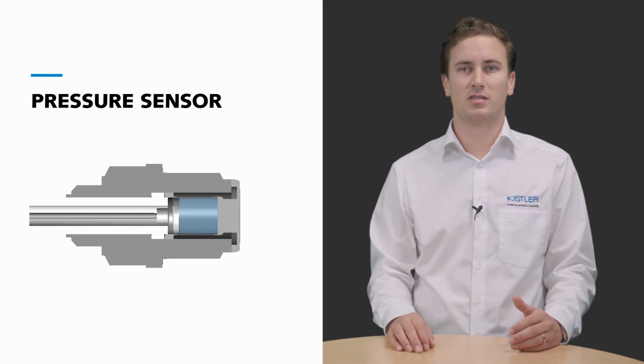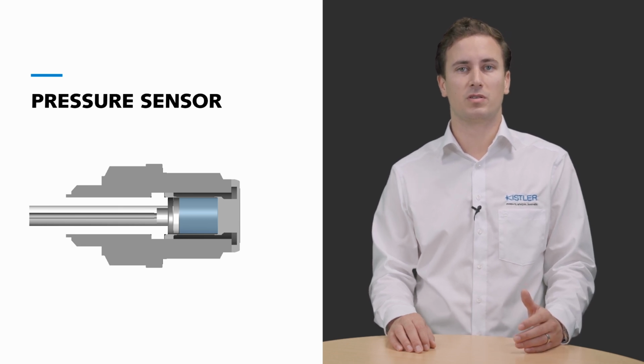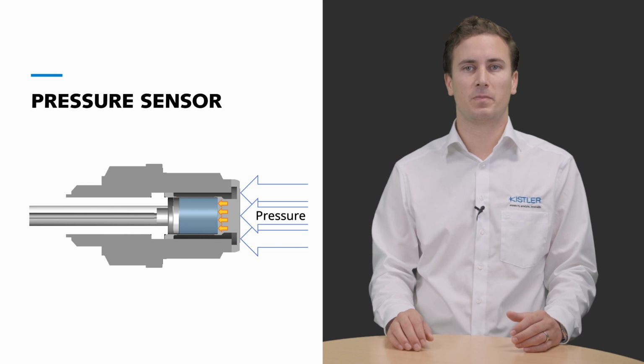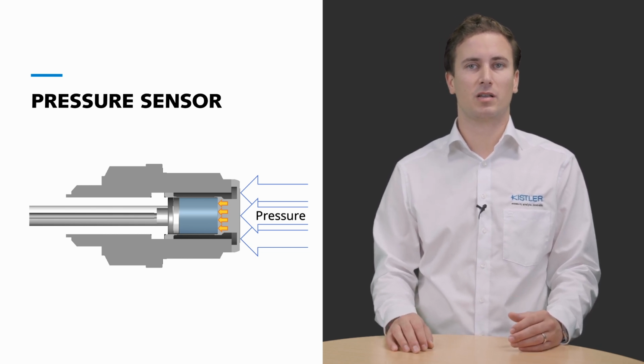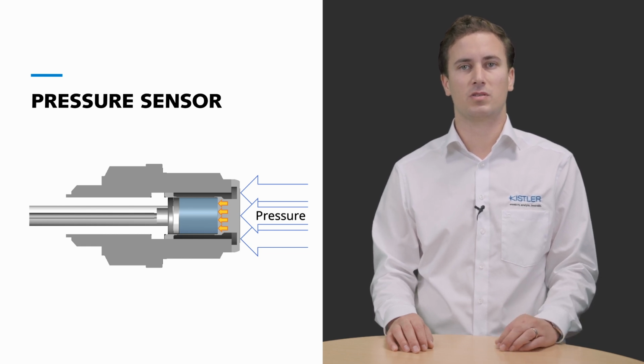When we take a look at this model of a piezoelectric sensor, we see that the pressure acting on the membrane leads to a force acting on the piezoelectric material. This is how we measure pressure, and the thermal effects we will take a look at all change how the pressure at the membrane affects the force on the sensing element. Now that we have the basics covered, let us review the three most important thermal effects for single event measurement.